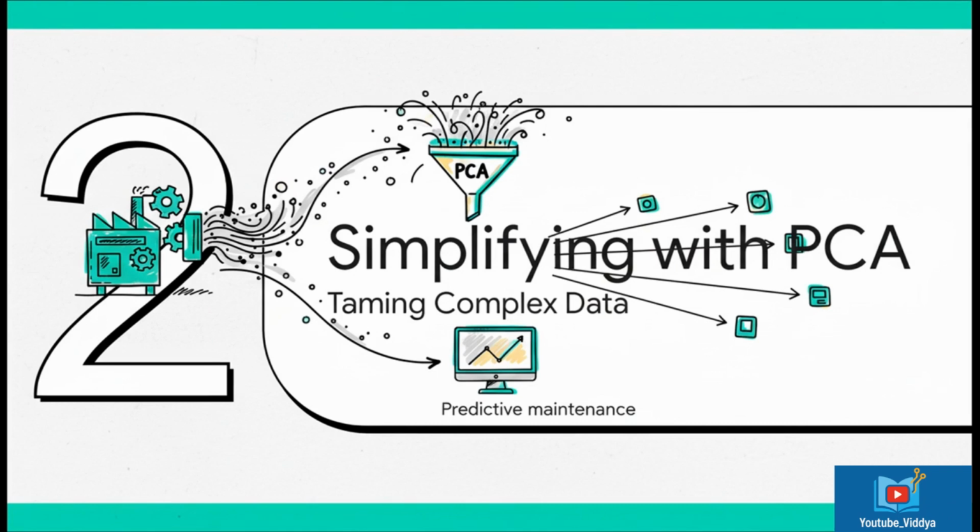Okay, so let's say you've done all that. Now you've got dozens, maybe even hundreds of different features from all your sensors. RMS, kurtosis, spectral energy, you get the idea. So how do you deal with all that? How do you simplify it without throwing away the important stuff? Well, that's where a really cool tool called Principal Component Analysis, or PCA, comes into the picture.